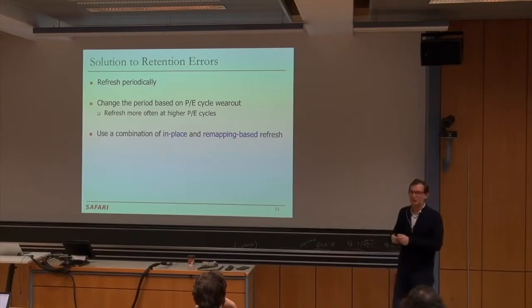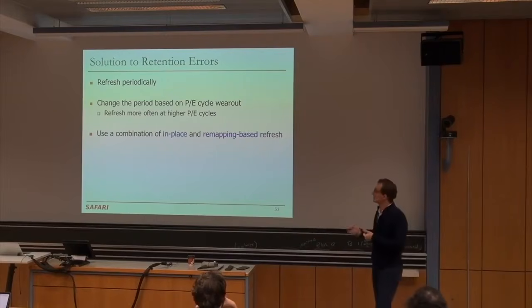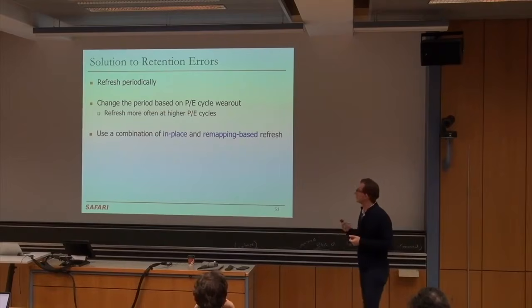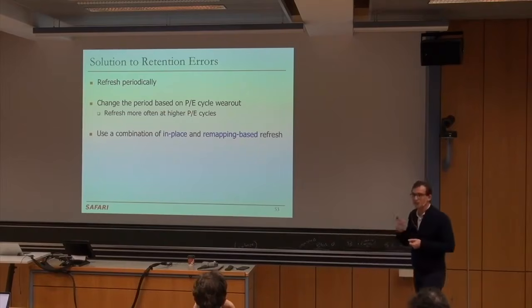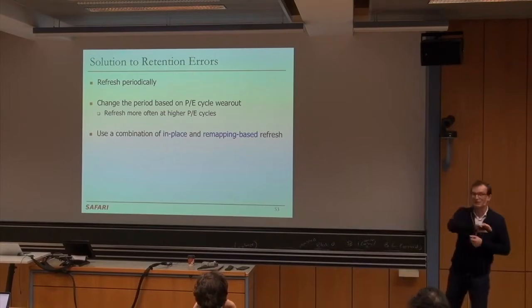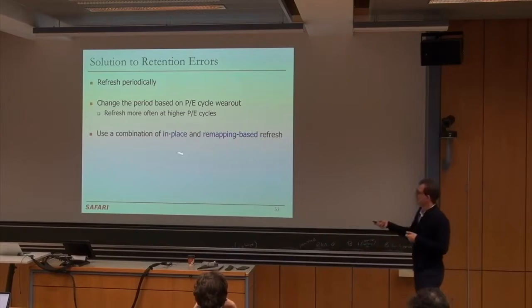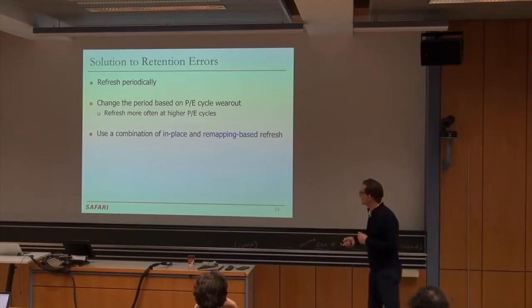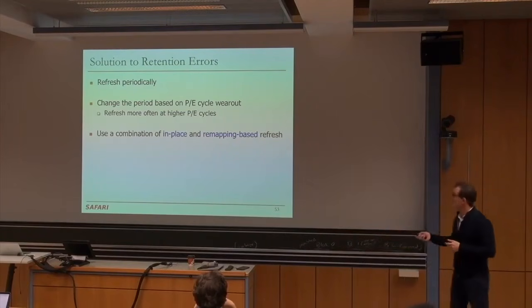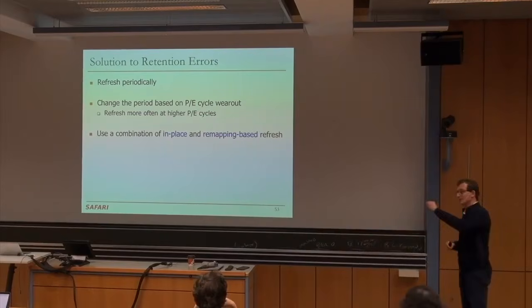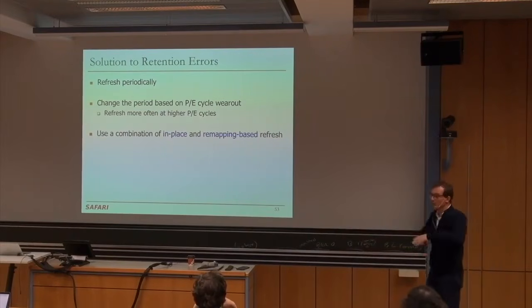If you can increase the voltage, in refresh you need to increase the voltage, which means that you can actually program that particular page, you need to refresh it in place without moving it somewhere else. So that's one of the ideas that's employed in existing drives right now, but that may not always be a good thing. Sometimes you may want to remap this particular page or all of the pages in this block